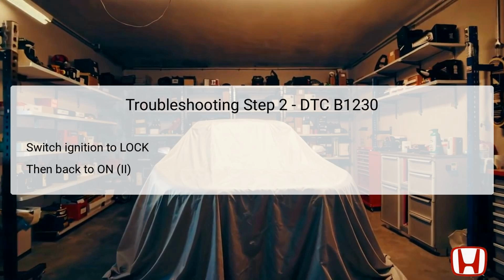By moving the ignition switch through these positions, the vehicle's computer registers this change, essentially rebooting the system. This process can resolve minor glitches in the electronics while allowing the climate control unit and sunlight sensor to reset. It also prepares the system for the next part of the diagnostics, making certain all operations are reset and ready for further checks. This step is critical in ensuring that all components are functioning during the diagnostic self-test.